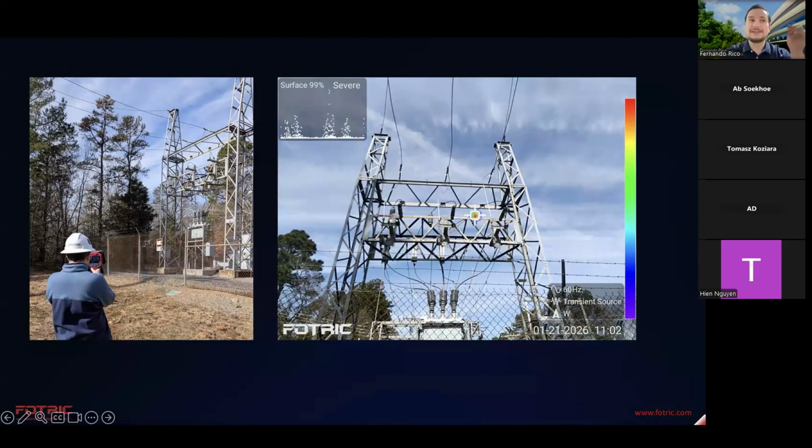Following that, they re-energized and they kept hearing the noise. So on a different week, they prepared more components, de-energized again, and replaced the other three in the back. To their surprise, the cracking noise was still there, which represented for them an issue that could lead to a potential fire, full failure of the insulator, and of course a failure on the line, on the system.